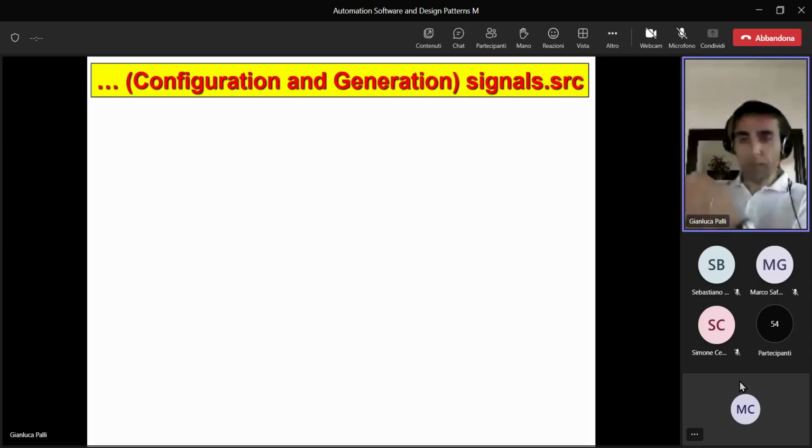Is another PLC, and actually inside this PLC you have at least two parallel different ways of implementing the mechanism for safety reasons, and they have to agree. Otherwise, it means you have some issue in the safety. And this also generates safety outputs that stop the machine, because it means you have some problem in the safety, and if you have problems in the safety, the machine can't run at all.